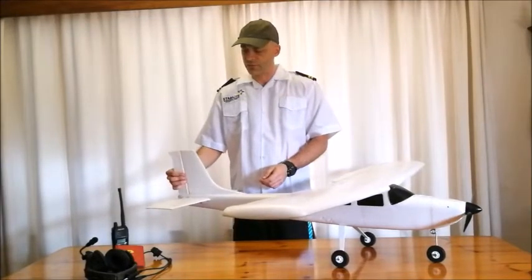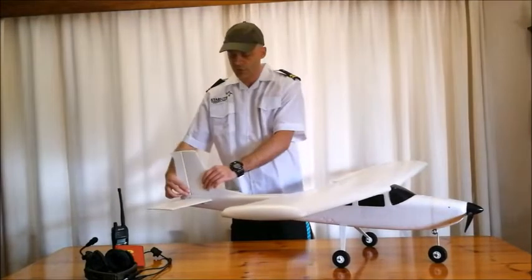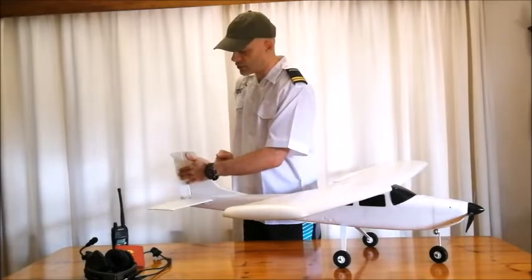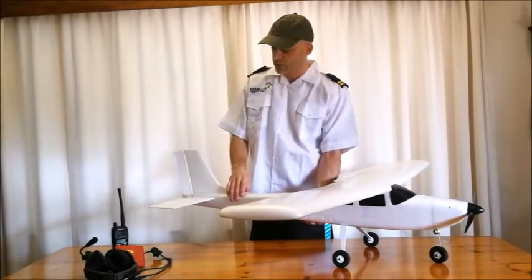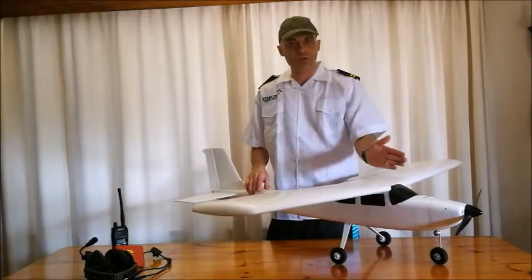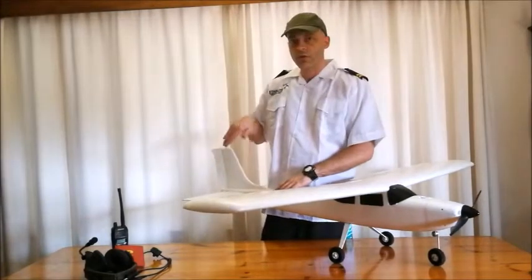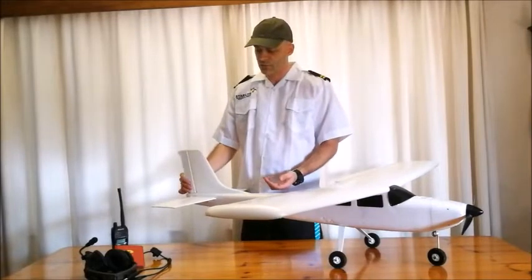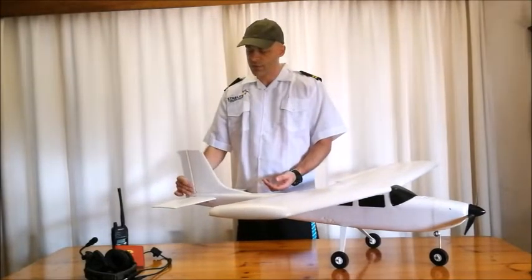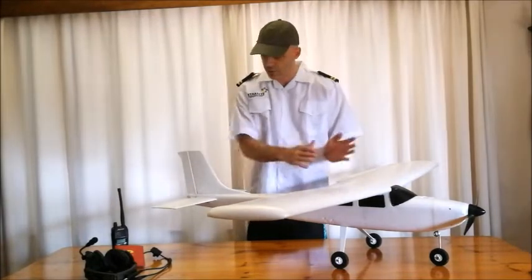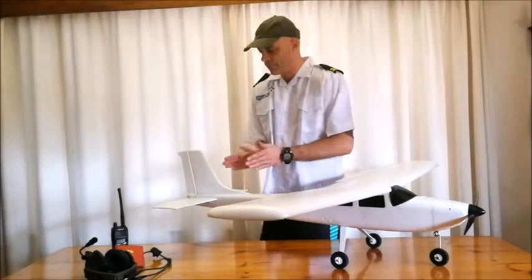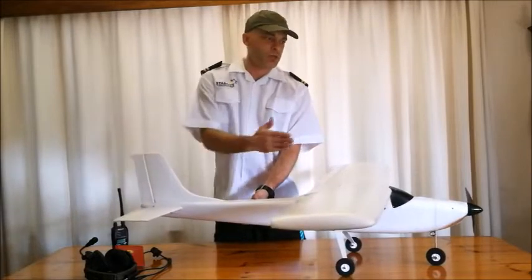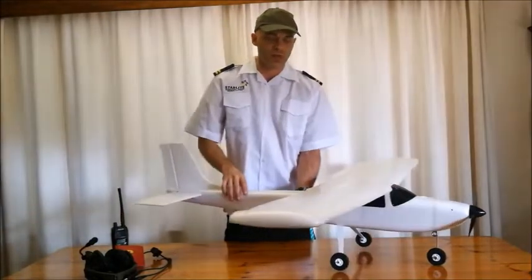Your yaw motion happens with the tail. So how this rudder works is that, let's say it moves towards you, then the air is going to flow and hit this rudder, and it's going to push the back towards the left, which is going to cause the airplane to yaw towards the right. So the tail or the rudder is able to control the yaw motion of the airplane. The same thing happens if you move the rudder in the opposite direction. The wind will come past and hit against the rudder that is facing towards me. It will push the tail towards the right, which will cause the nose to go towards the left, and so it will yaw towards the left.